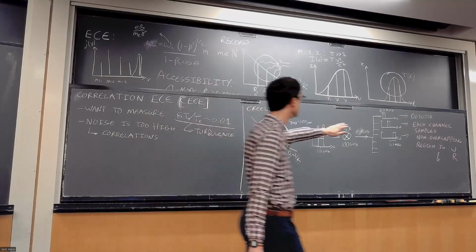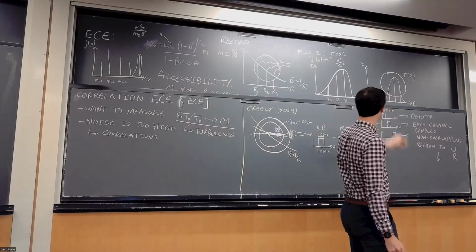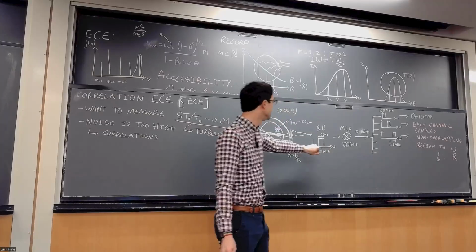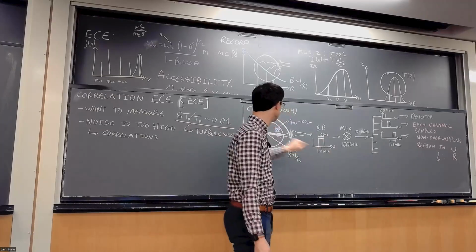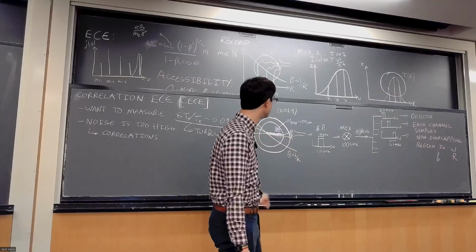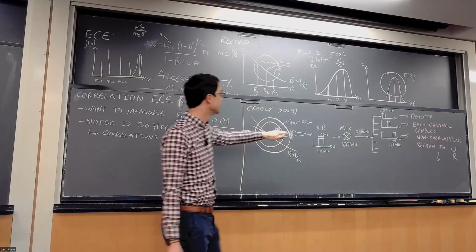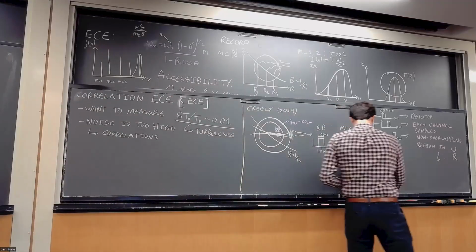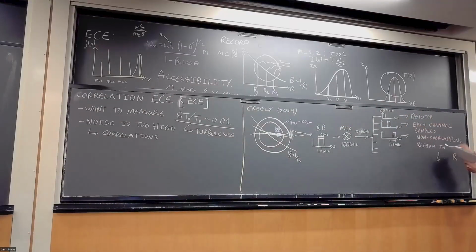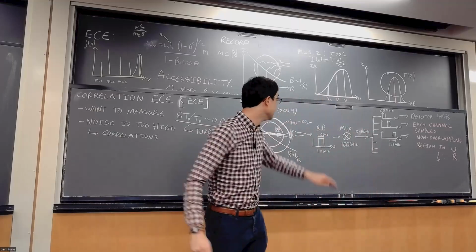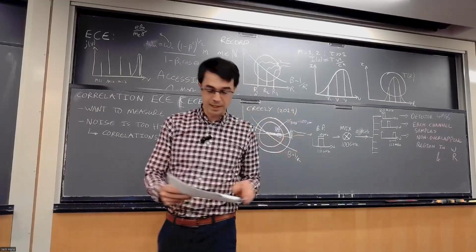And you can tell that these regions are very small because we're dealing with 100 megahertz bandwidth, and we originally started with 110 gigahertz here. And so you see we've gone down by a factor of 1,000. If 110 gigahertz was roughly enough to cover this entire region here, then we're now dealing with regions which are 1,000 times smaller than the radius of our tokamak, and that's how we're able to get down to this sort of 100 microns or so. And we digitize these signals, and just for your reference, the reason why we downmixed is that digitizing is now much less expensive. We're doing it at something like 4 megasamples a second, and that is quite an affordable digitizer compared to the ones you would need to digitize this signal up at hundreds of gigasamples a second.